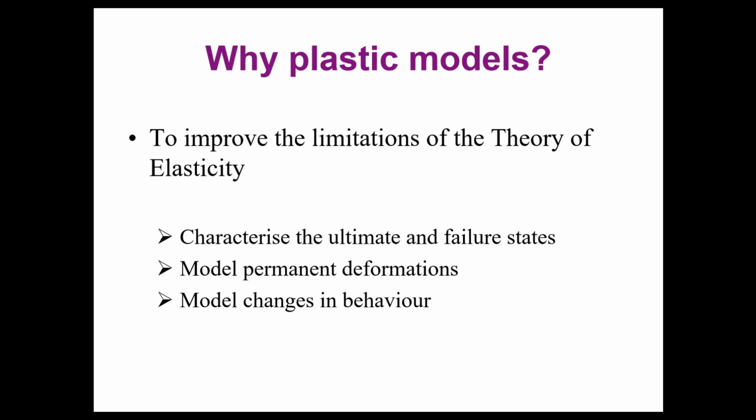The third reason to study plastic models is to capture the change in behavior, because especially when you study metals, for example steels, that is the metal you study the most when you are a civil engineer, you notice that there is a first regime, a first stage, where the relationship between stresses and strain is certainly linear and elastic and isotropic in many cases, but after that there is a change of behavior to a more plastic or viscoplastic or any other non-linear behavior that is not isotropic linear elastic anymore.